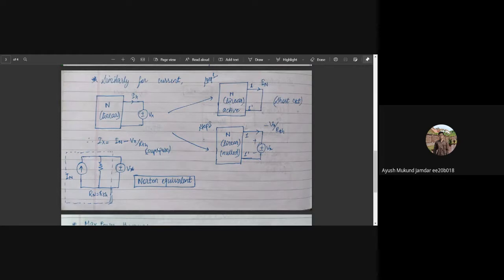In the same way, we have, let's say, a big network of linear elements, resistors, voltage sources, and independent sources. Let's say we again have a terminal from two nodes, and across the terminal we again put up a resistance. We found that the resistance has a potential drop across it, Vx, so we replace it by a constant voltage source Vx, and a current Ix flows in this given direction. So this is what the situation is.